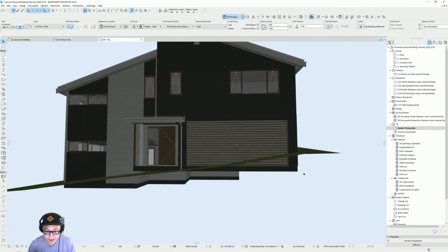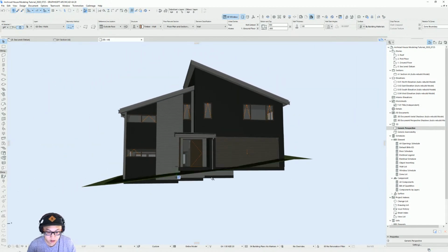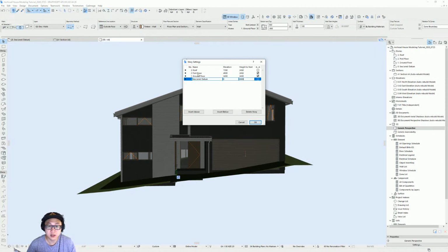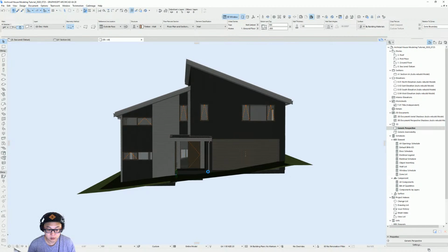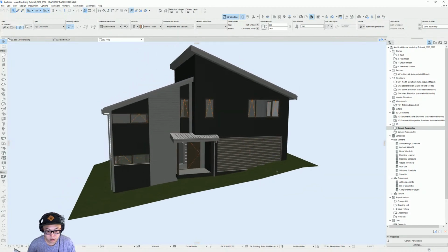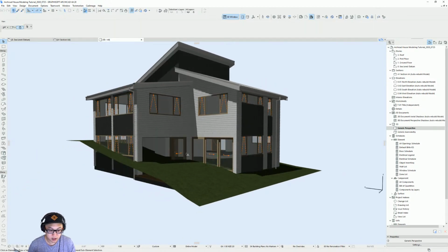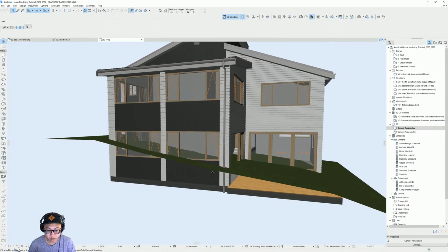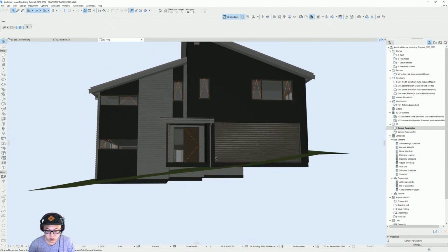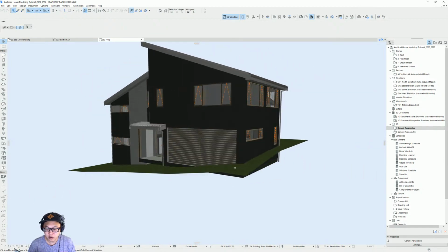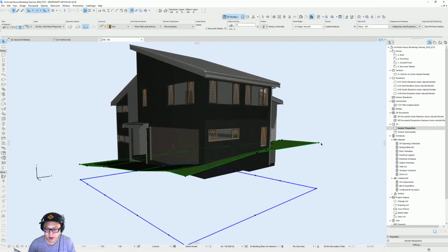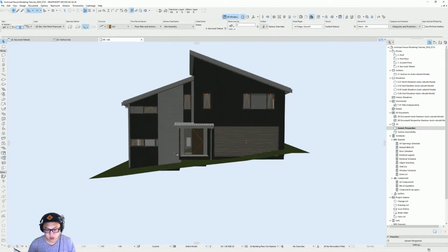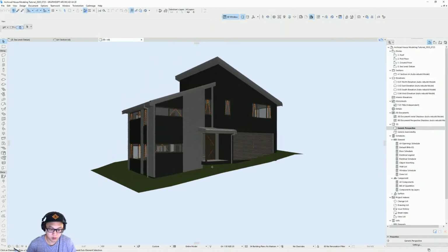Okay, so now we get a mesh, and actually maybe I can raise the ground level a little bit more to, let's say, 2.6. The house has shifted again a little bit, and yep. So let's say that's our terrain. So here we actually need a lot of earthworks to kind of remove this. Or what we could do is maybe manually tweak our mesh so it's not that high. Oh, anyway, doesn't matter. What I'm going to show you next is how to do a little bit of earthworks.